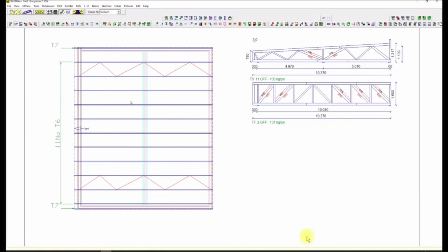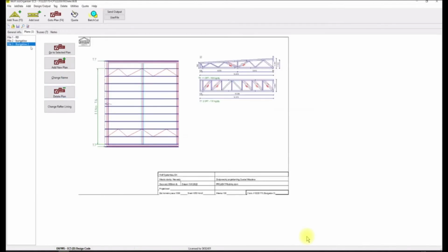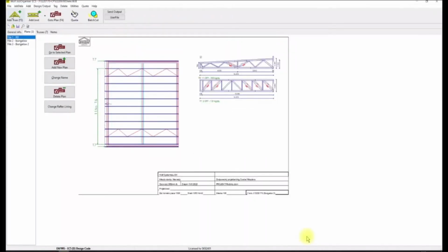That's why we are using sketch lines, and then we design the wind girders manually in 2D, as you showed now. The wind girders can't be properly displayed on the plan, so they are shown using these auxiliary lines, and the wind girders themselves are created in 2D, simply as a separate truss.